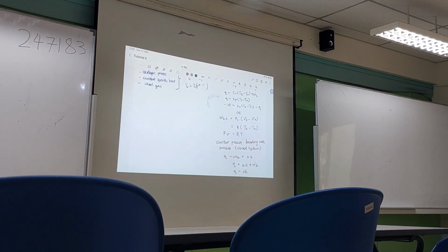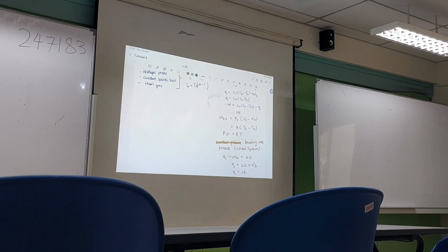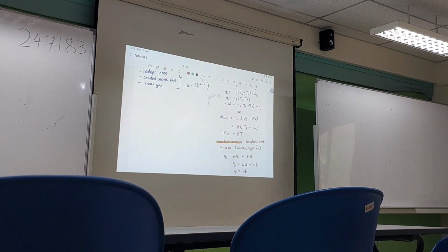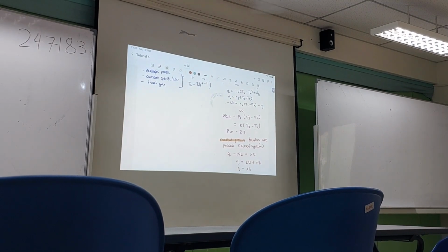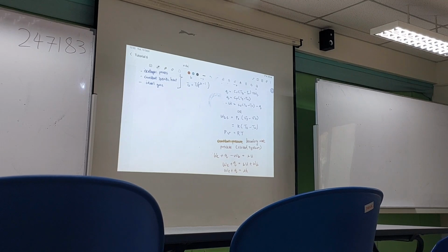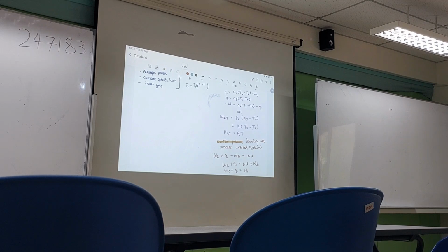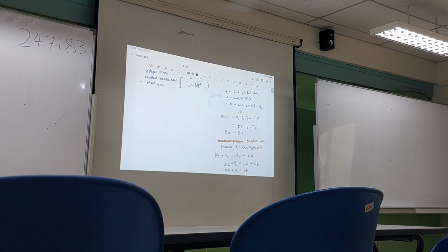It's the same thing that I showed you for the test as well. So this only holds true if this, okay? If you have any other type of boundary work, you cannot do it. It must be a constant pressure process. Otherwise, the value won't tally. So let's say your process has an additional electric work, the electric work has to stay on the left. It cannot be moved over also. Only boundary work can be moved. Essentially, you can think of it as flow energy. That's why it becomes enthalpy. Not the same thing, but similar.